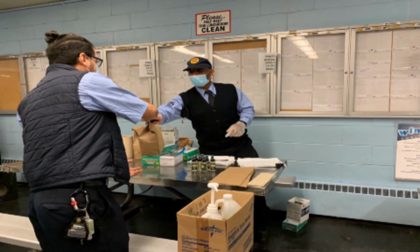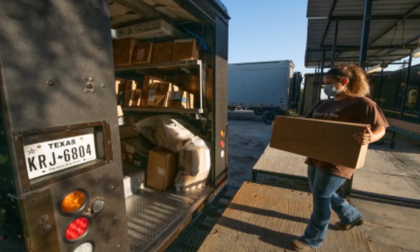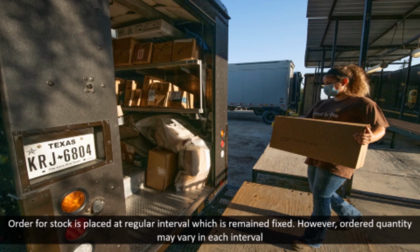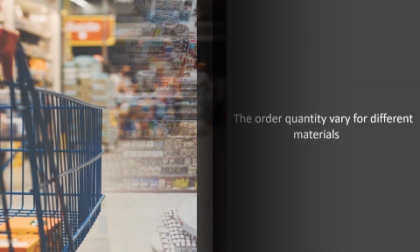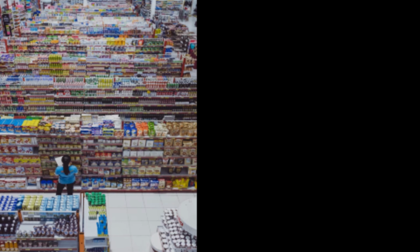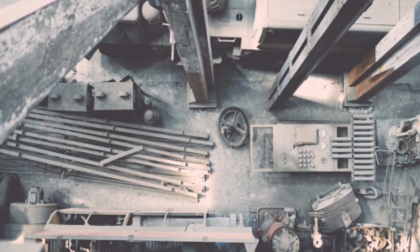The stock position of each material of a product is checked at regular intervals of time, and the order for stock is placed at a regular interval, which remains fixed. However, order quantity may vary in each interval, because your periodicity is fixed, but the quantity of ordering is not fixed. The frequency of reviews varies from organization to organization. It also varies among produced products within the same organization, depending upon the importance of the products, predetermined production schedule, market condition, and so forth. So the order quantities vary for different materials.